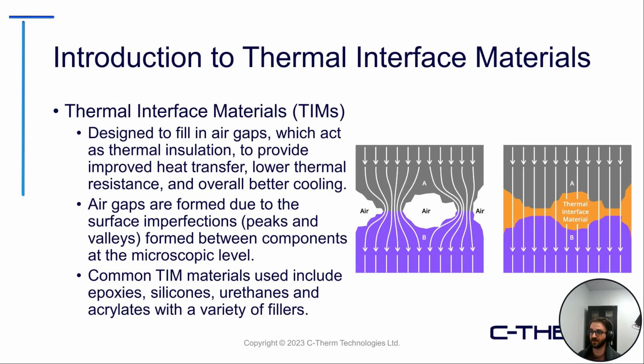Thermal interface materials are essentially designed to fill those air gaps, those voids that will be present between surfaces of typically a heat generating electrical component and a heat sink. So of course, these TIMs help to improve the heat transfer, lowering the thermal resistance, and improving overall performance.